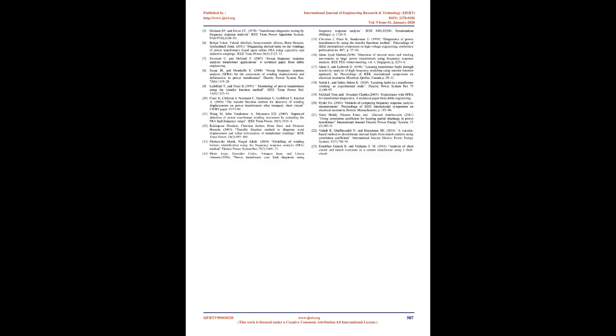Table 3 illustrates the results of applying the indicators to the normal and faulty responses of phase U of the transformer taken by HV, LV, and interwinding measurements. The corresponding measurement results are shown in Figs 5, 12, and 13. The spectrum deviation for the responses related to the LV winding reaches high values in the 100 Hz, 1 kHz, and 110 kHz decade bands, where the changes caused by the interturn fault are most apparent. The spectrum deviation between results from interwinding measurement is very close to zero throughout all the frequency bands. This is a good indication of less sensitivity of interwinding measurement in detecting interturn faults.